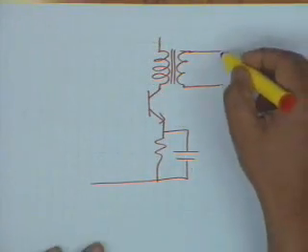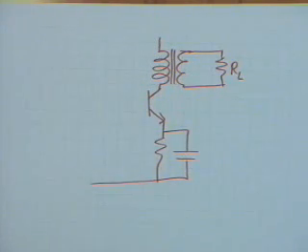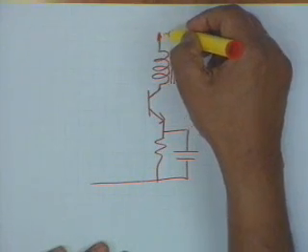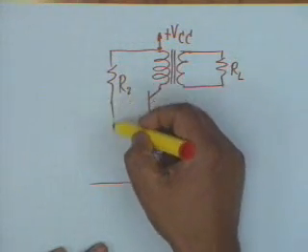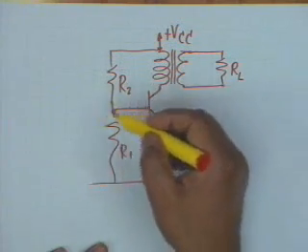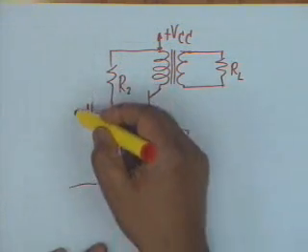In the last lecture, 32nd lecture, we had discussed the power amplifier with a transformer coupling. That is, what we had was the usual transistor biasing circuit. Instead of a resistance in the collector, we had the transformer primary, and to the secondary is connected the load, actual load RL, which could be a loudspeaker, and then this goes to plus VCC, and the usual biasing circuit, there is a resistance R sub 2 and a resistance R sub 1. The input signal is applied between these 2 points.